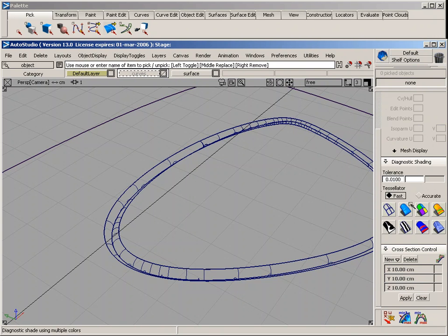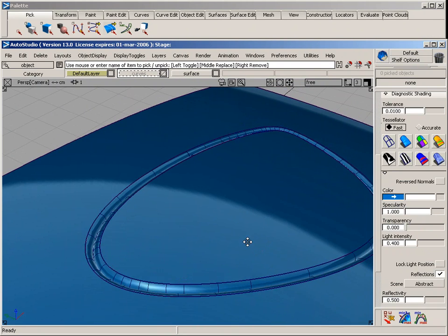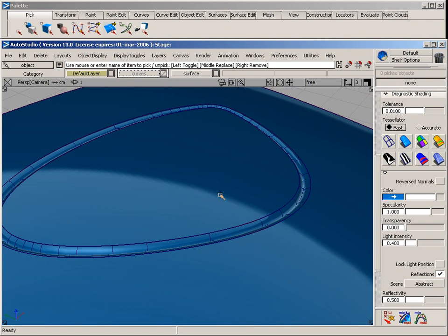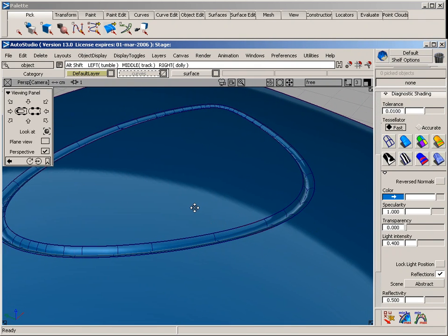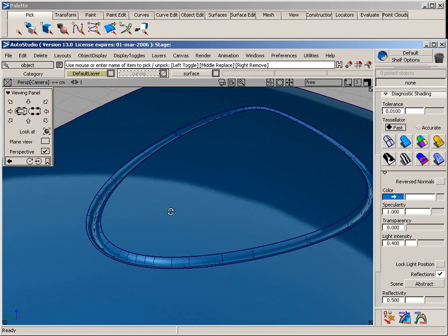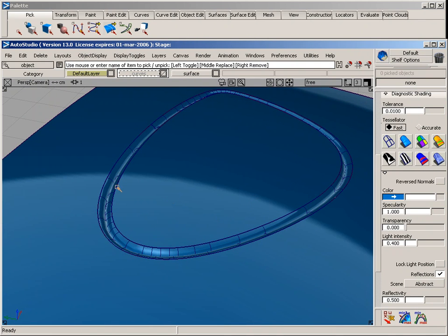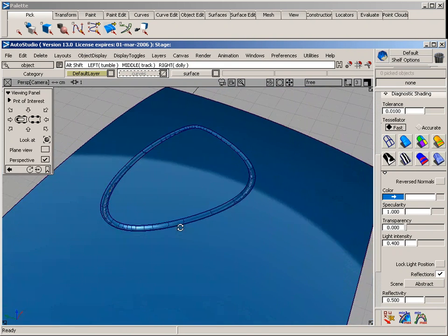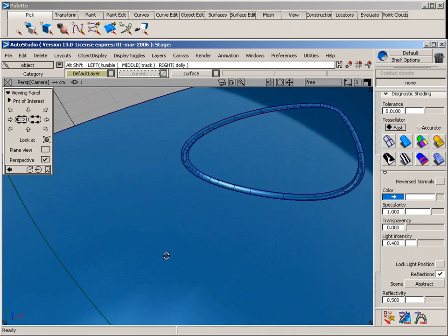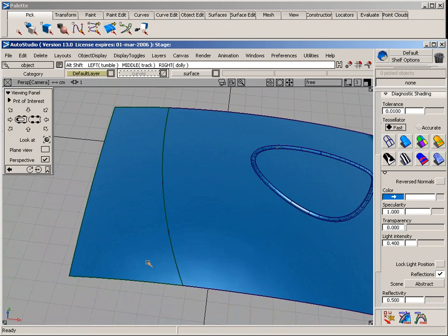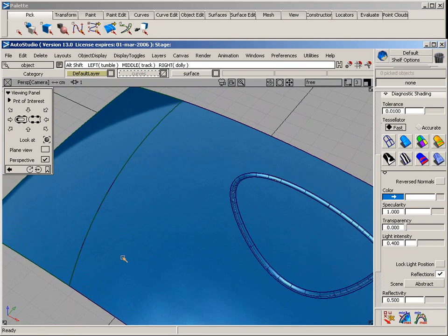However, just for evaluating the surface, if you take a look at this, you can start to see exactly what this part line is. Now keep in mind that this is not a true part line because it actually comes to a point. Most often a part line would actually have a small gap in between these 2 fillets, and that's what I'm going to try and create over on this side with the tubular flange tool.